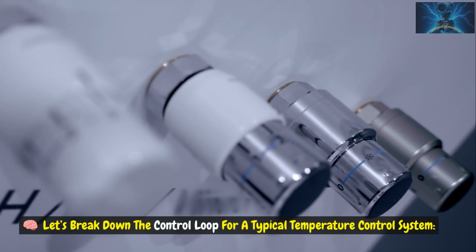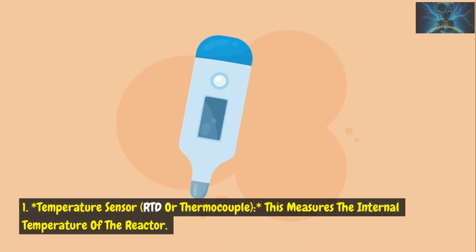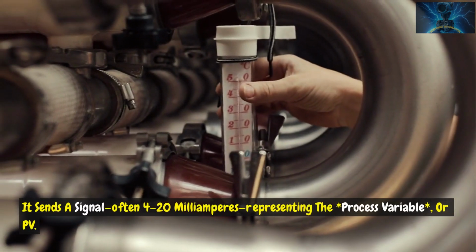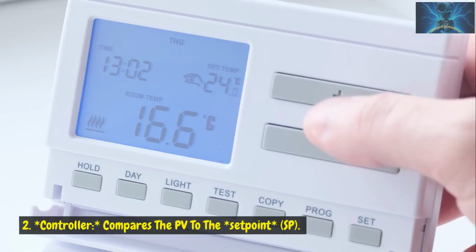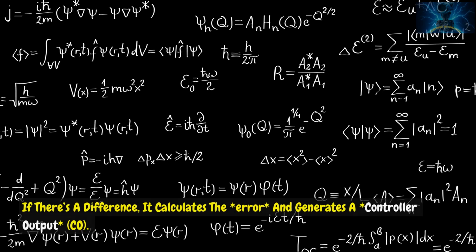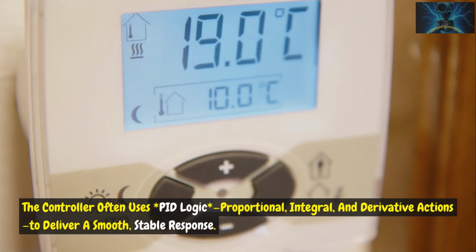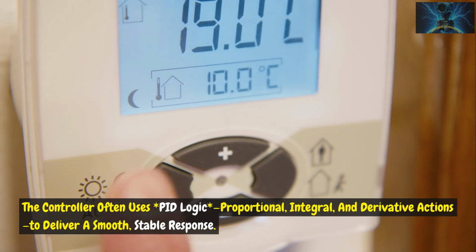Let's break down the control loop for a typical temperature control system. 1. Temperature sensor, RTD or thermocouple. This measures the internal temperature of the reactor. It sends a signal, often 4 to 20 milliamperes, representing the process variable, or PV. 2. Controller compares the PV to the set point, SP. If there's a difference, it calculates the error and generates a controller output, CO. The controller often uses PID logic, proportional, integral, and derivative actions, to deliver a smooth, stable response.